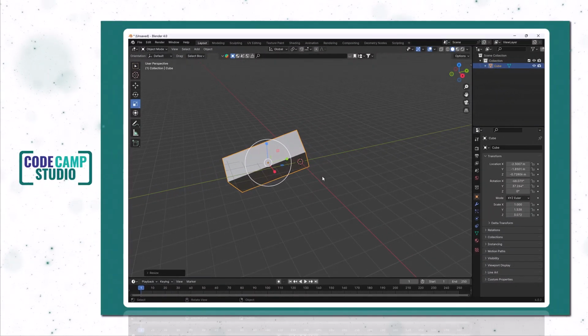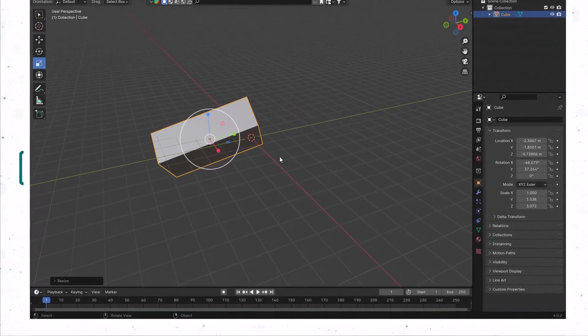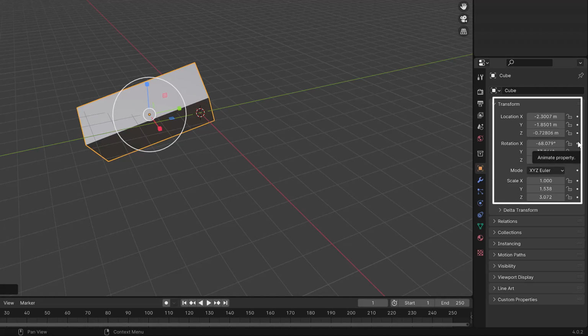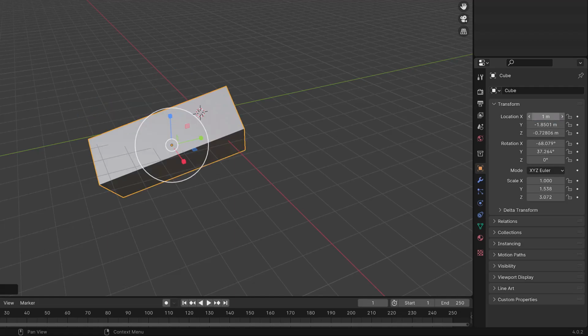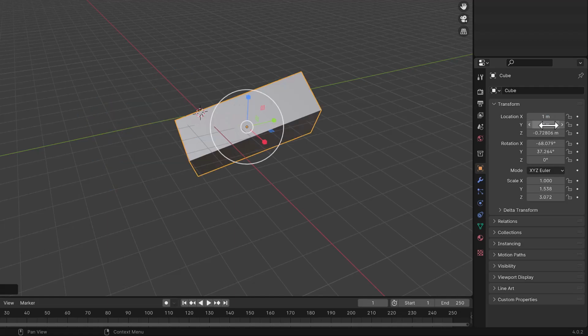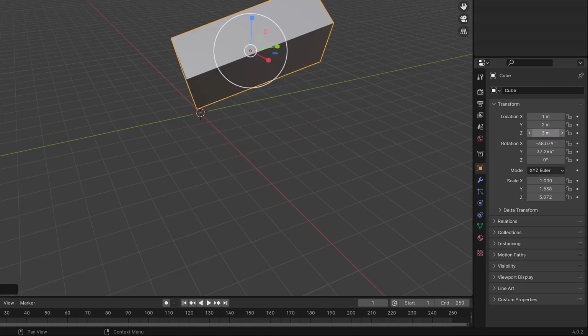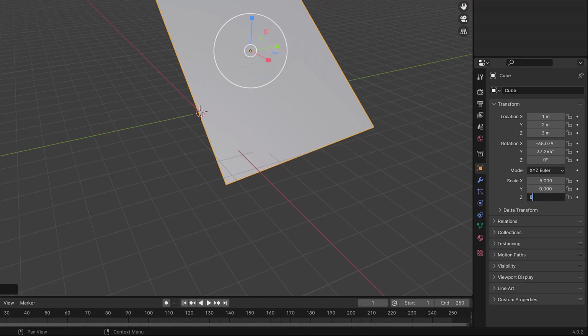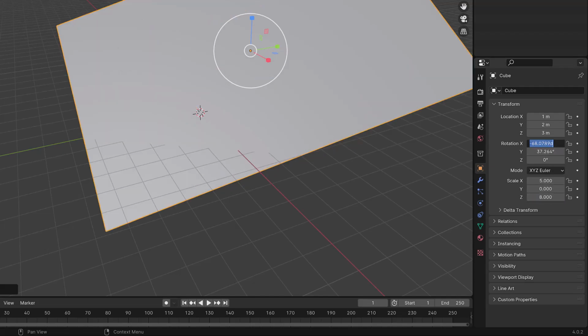However, there is another way to perform these actions, the Transform panel. This panel, typically located on the bottom right side of your workspace, offers numerical values for precise adjustments. Once the object is selected, you can directly input values for X, Y, and Z coordinates to move your object, adjust the scale percentage for scaling and define rotation angle in degrees.